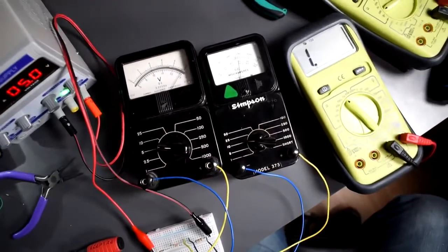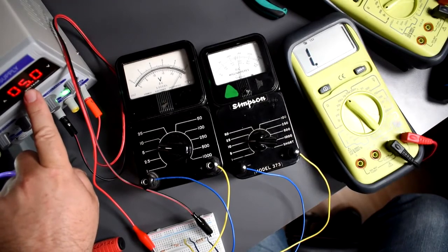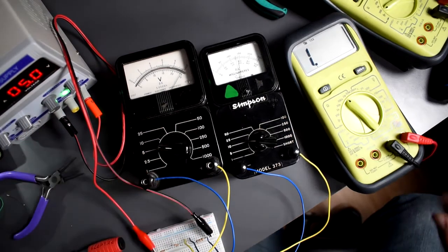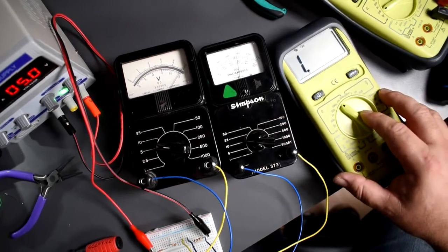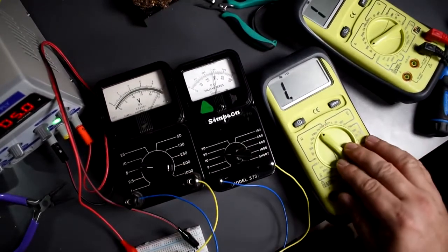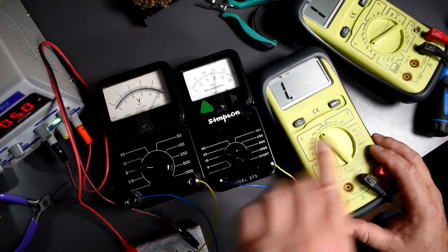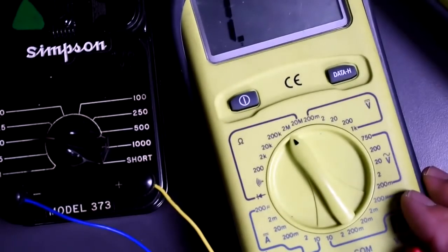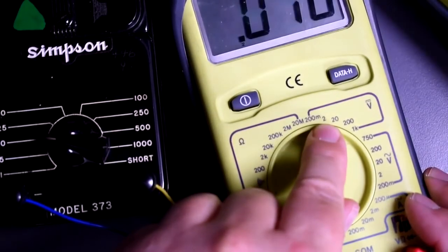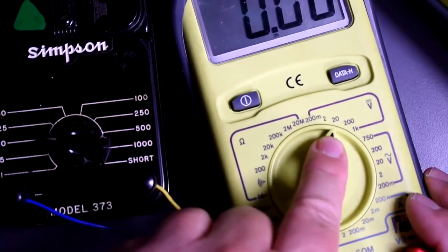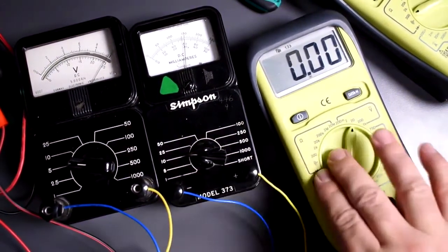Okay, so the internal meter on the power supply shows 5 volts. I probably would trust this more than that right now, but let's take a look. I'm going to set this multimeter as a voltmeter. So we're measuring 5 volts. What's the range we're going to choose? 2 volts? No, because 2 volts is not enough to measure 5 volts. So the range of up to 20 volts right here is going to be the next higher. So that's going to give us the most accurate reading with this multimeter.